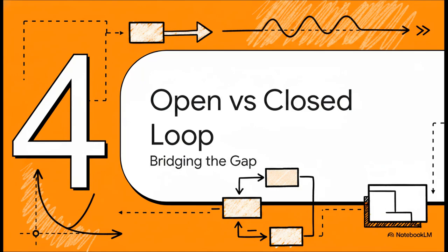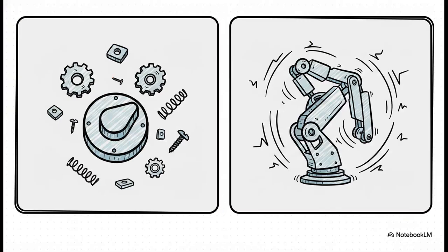Section 4, open versus closed-loop systems. So we map the open-loop behavior to definitively count the closed-loop poles hiding out in the unstable right-half plane. Think of open-loop dynamics as your raw materials. They're measurable right there in the lab, and we can easily inject a variable gain, which we represent with K, just to see how the system reacts.